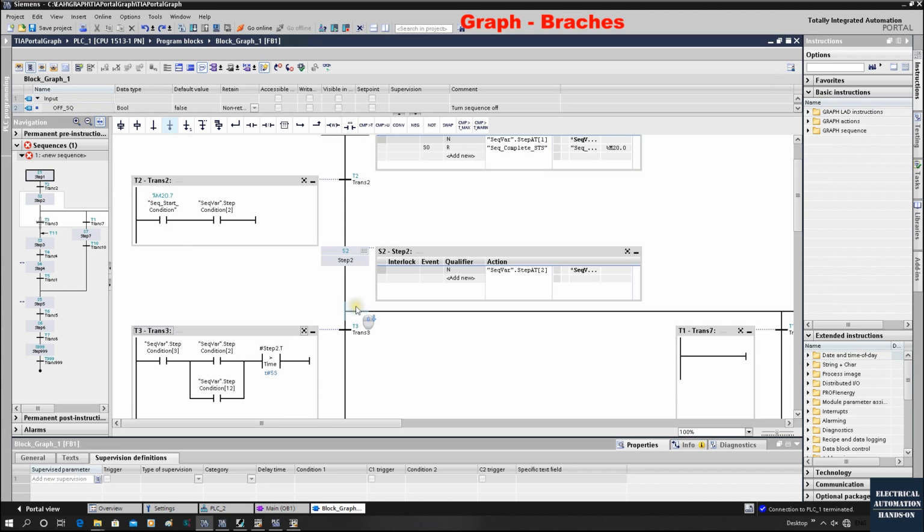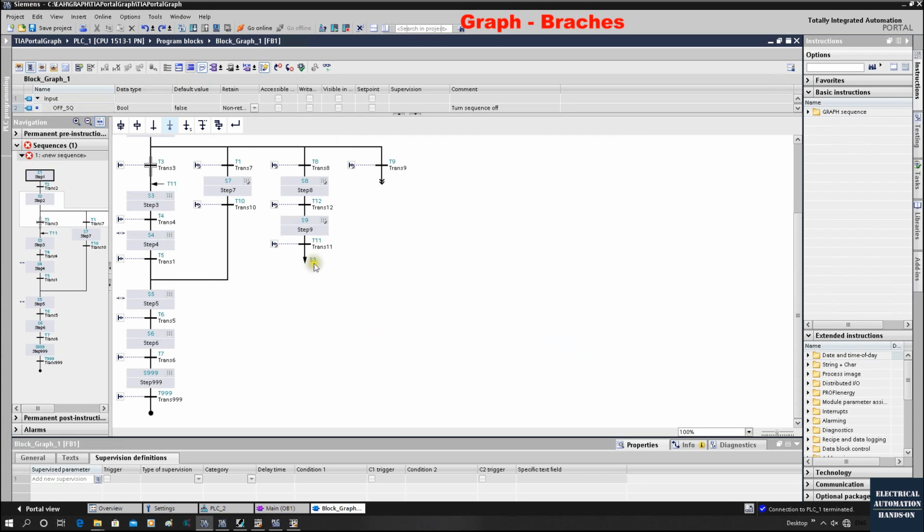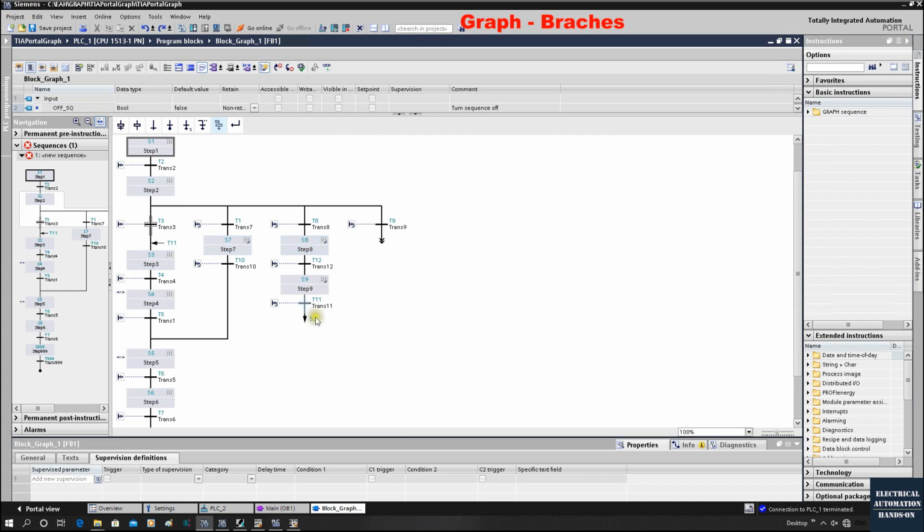If you are doing step-by-step commissioning tests, this will be very easy. But basically, once you finish all the specific sequence tasks, then you can close this style, and just monitor which step is running to have this global picture view. Okay? And then we can also see this main sequence now is using 2, 3, 4, 5, 6. Then if you add something new, for example, now if I'm trying to add a new sequence here, then this sequence is 10 and 7. This number looks very messy, right?